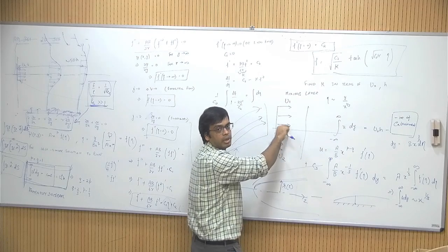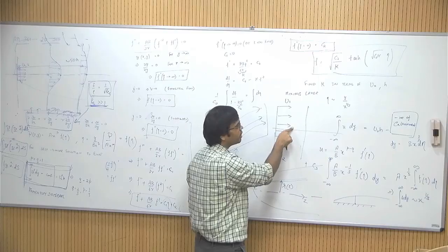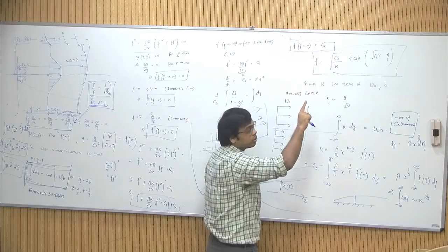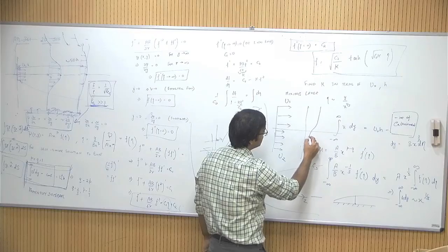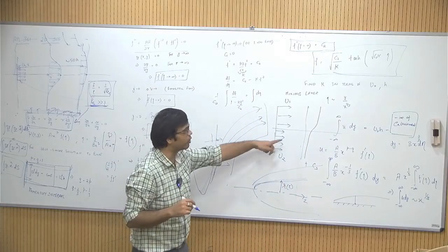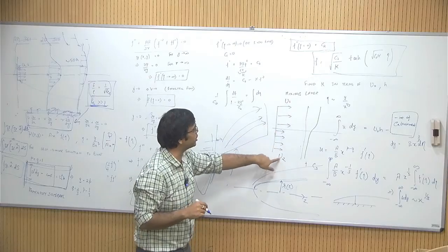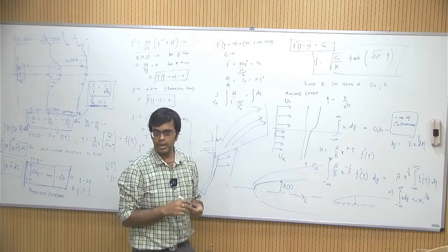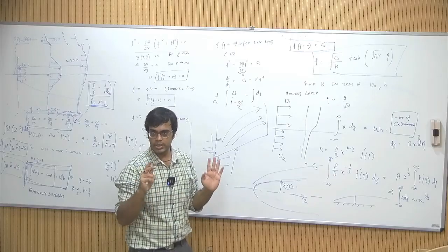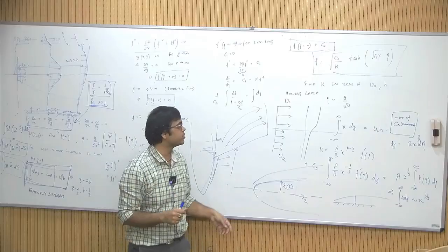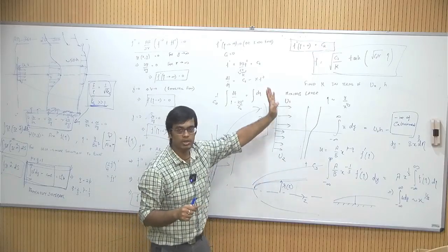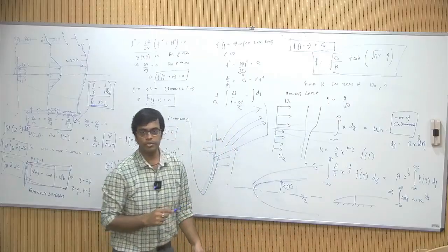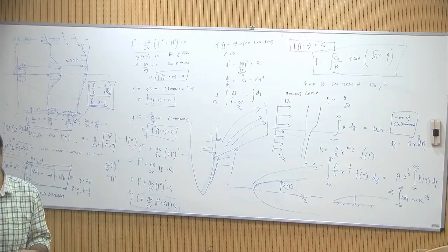there is a deficit of momentum, there is a difference in momentum. So, you can imagine there will be a huge viscous stress on this. Okay, and as you let it flow downstream, the viscous stress will result in some diffusion of this jump of velocities. Okay. So, u2 will try to diffuse into u1, and u1 will try to diffuse into u2. You can think of it like concentrations as well. The governing equations are non-linear. In concentration cases you will get a linear governing equation. So, these will try to diffuse into each other. Okay. So, you can formulate these layers and you can formulate the analytical solution of the self similar equations here.